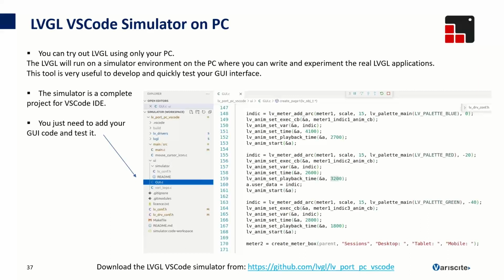Keep in mind that it has been designed for microcontrollers, not for MPU. So the target of this framework is to be extremely compact. We tested it with DART-6UL using the frame buffer. We also tested it with our i.MX 8M families, and it's working the same. So on this platform, you will not have specific memory constraints compared to MCU, but you can always strip the application down according to your needs and just enable whatever you need only.